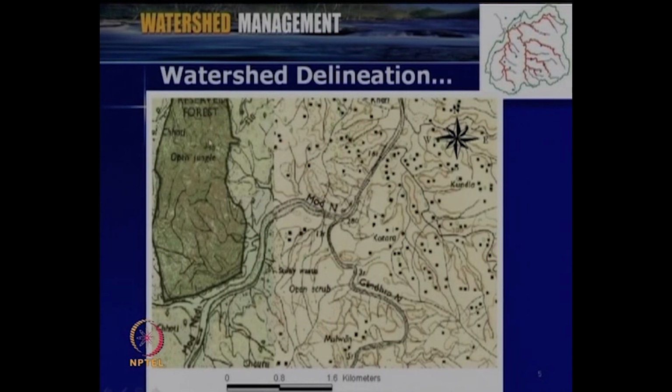So, this figure shows a typical topo sheet or topographical map. You can see that it gives the land use, like the reserved forest, then the agricultural land, then the rail network, road network, then the drainage pattern, and even the location of lakes. So, like that, various information we can obtain from such a topo sheet, or so-called topographic map.